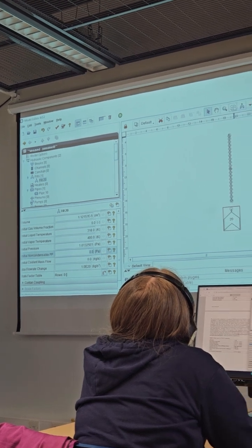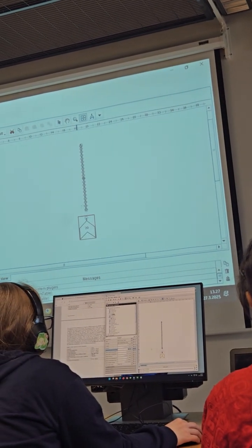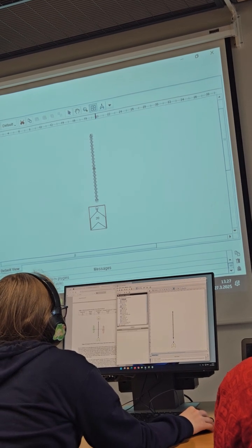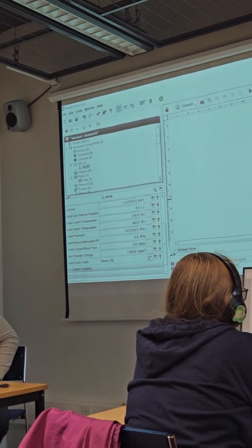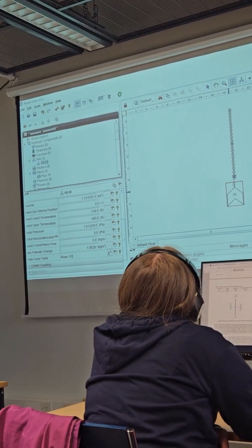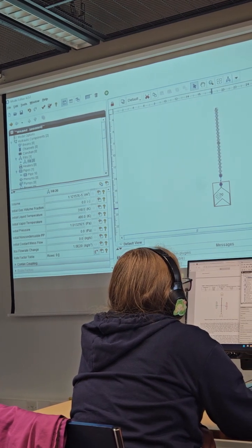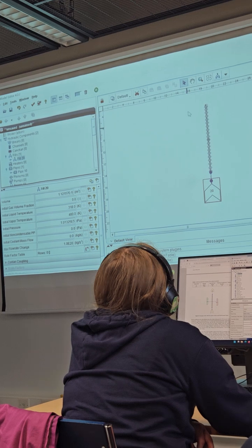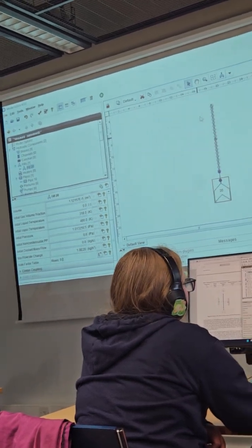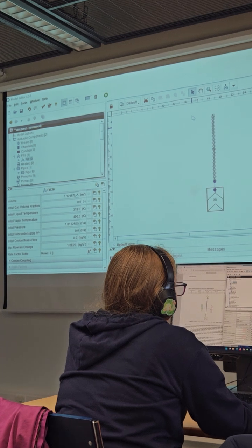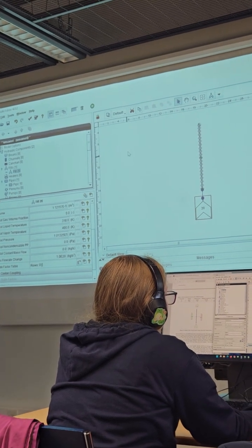One thing we just need to do is to connect this fuel component to the pipe. Click here on top of the connector, click on the outlet of the fuel component and the inlet of the pipe. Since it is connected to the end of the pipe, we don't need to define the cross connection angle, so it is kind of 180.